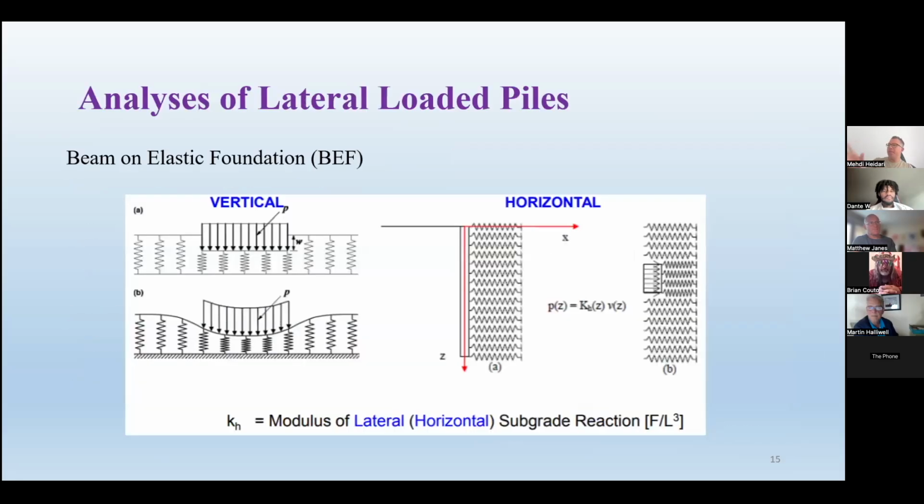So these are different models here, as you can see. Analysis of a laterally loaded pile, and this pile could be the caissons or any system that supports the excavation also, because again these are mainly laterally loaded substructures. This is the concept of a spring.